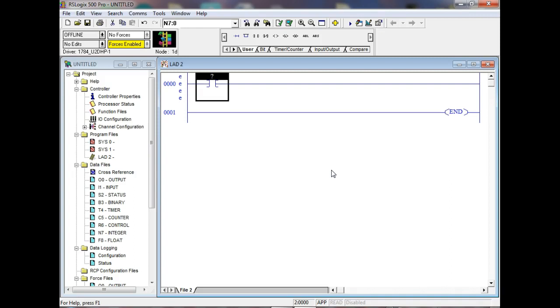So when I look at my inputs, I got I/0, I/1, I/2, I/3, I/4, then I got I/5, 6, 7, 8, and 9. So this guy's got 10 input ports, single bit input ports. And I have to tell it which one I want to use. So we start off by typing in I, which says I'm dealing with a what? Input. And then we put a colon. This is our separator between what type of port I'm going to, and then we start giving it the address.